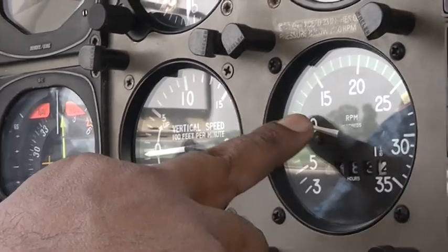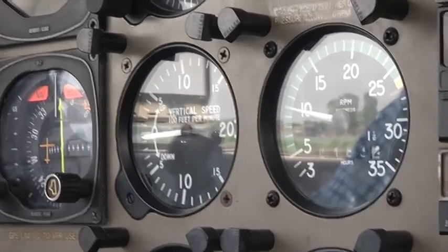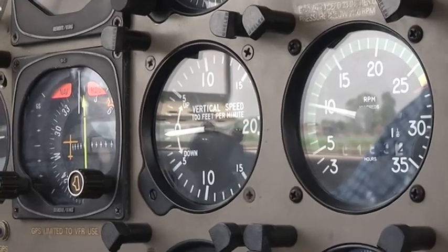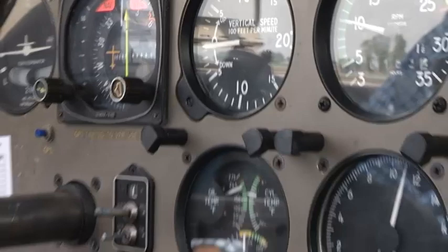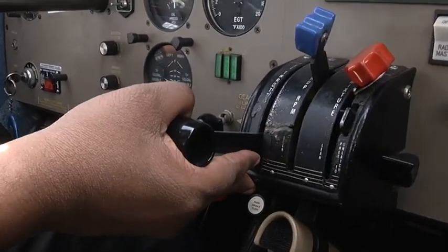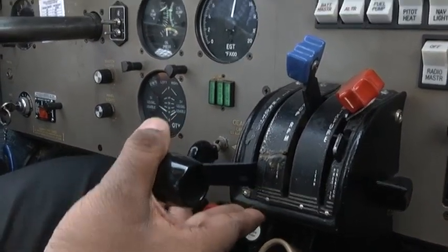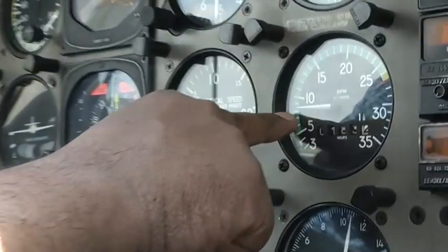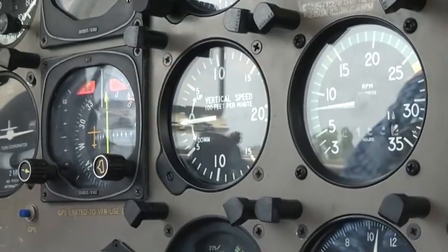You can see the needle is at 1000 RPM. Now with this 1000 RPM, I will move the throttle lever to the idle position. You can see this is the full throttle setting and this is your idle position, just the extreme. So now the throttle is at idle, and this is your idle RPM, something around 800, 850, and I will check